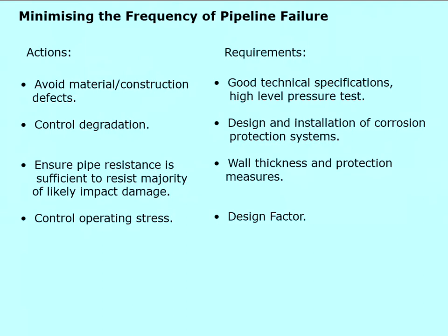And you've got to establish correctly the distance from population and infrastructure, and you've got to make sure that you maintain the minimum distance at all stages of the pipeline life, which means, because you're not in control of the land around the pipeline, you've got to keep going and looking and checking what's there, and then if there's something there that doesn't comply with your design, you've got to do something about it.